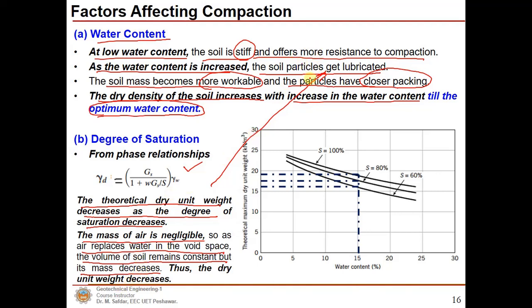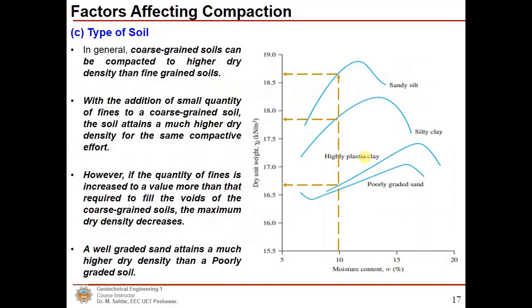But here we need to reach the optimum moisture content, and if too much water is present, the dry unit weight will decrease. And you can clearly see that as the degree of saturation is reduced, the unit weight has also been reduced.